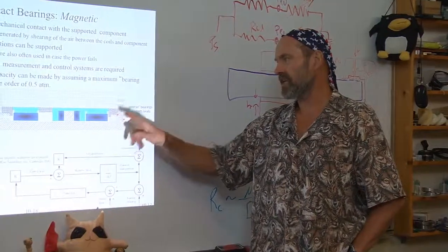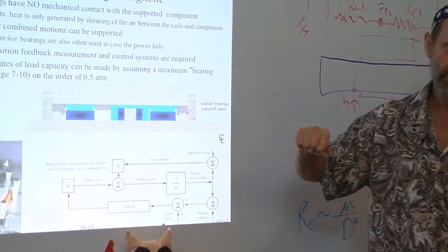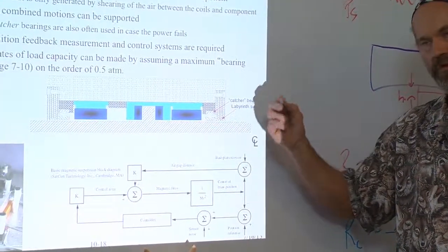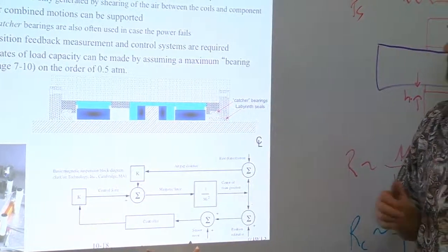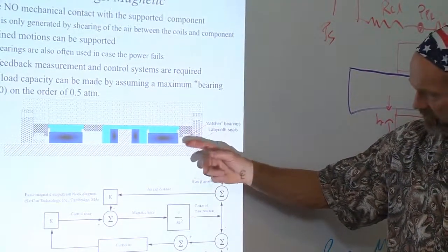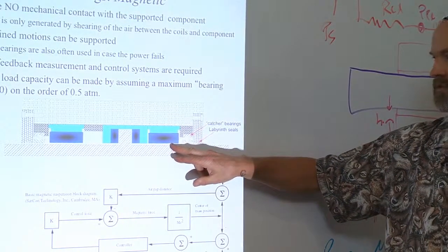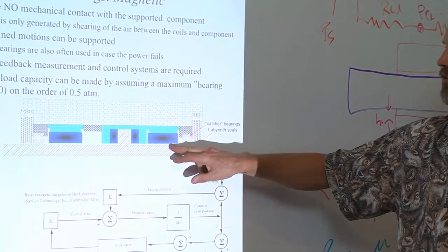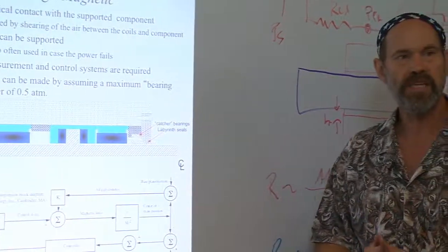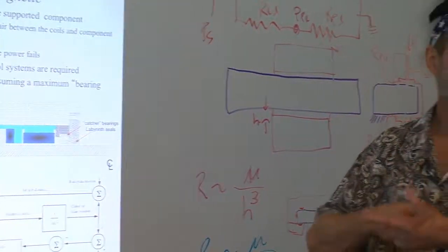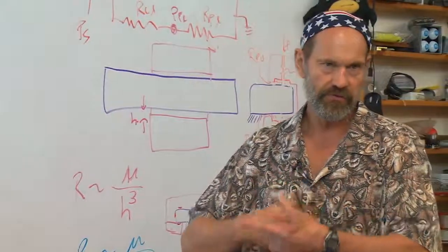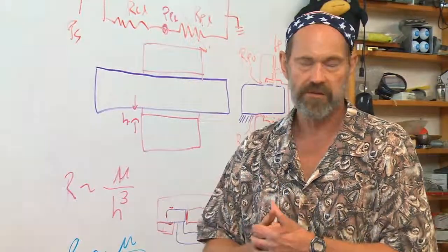Now you don't have to rely on a pump. You have a servo system, but you don't have to keep your fluids clean. And if you run it in a vacuum or with fairly large gaps that you could never run an air bearing at, you could run at incredibly high speeds without generating shear power or the friction of shearing a fluid in a thin, small gap.